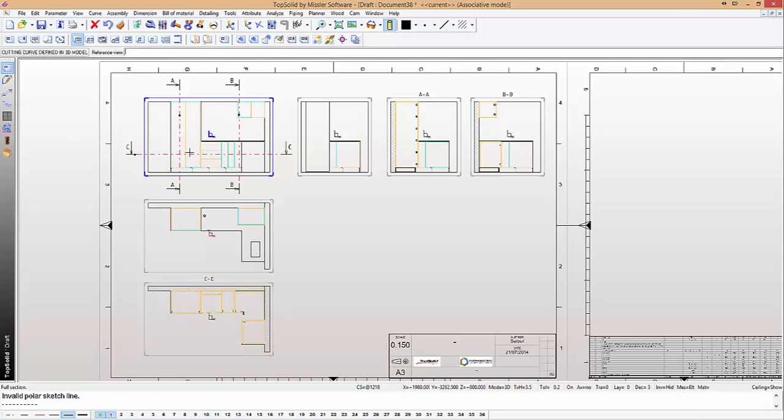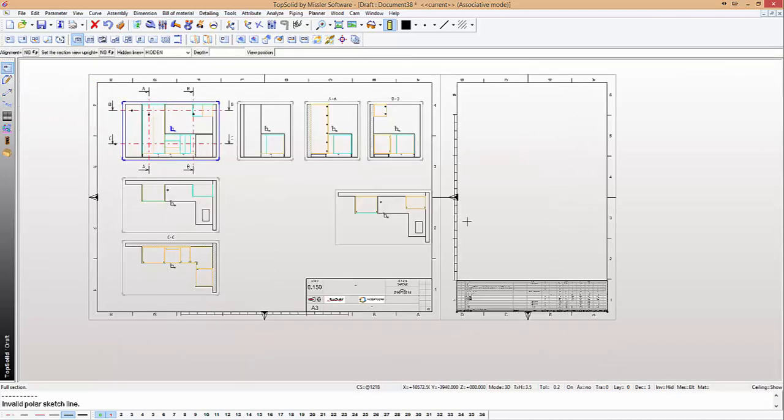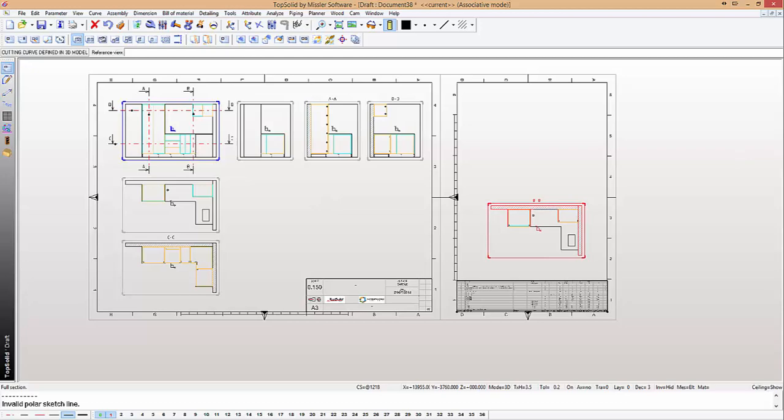Perfect. Now what you can also do is, of course, create a section, and if we create it along the top and through the wall units, you can say here, press OK. We don't have to align it, so we could just move it over into this plot page if we think that we're running out of space here. Okay. Now let's create a few detail views.